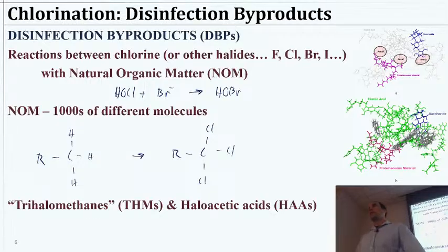And those can be even worse because brominated things are more toxic than chlorinated things. So if we have situations like that, we want to be pretty careful, especially if we're doing something, let's say, with brackish or salt water. Now, that's kind of atypical for what we normally think of for water and wastewater treatment. Perhaps our wastewater, though, has a fair bit of chloride, and maybe there was some source of bromide addition. So then we might be concerned.